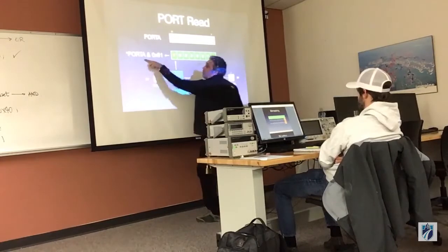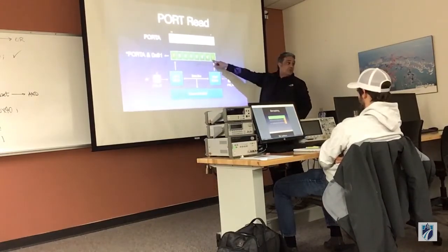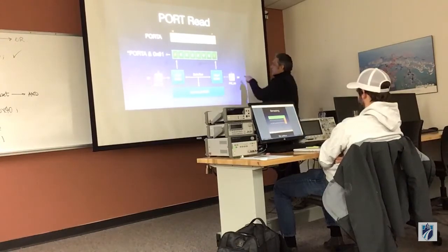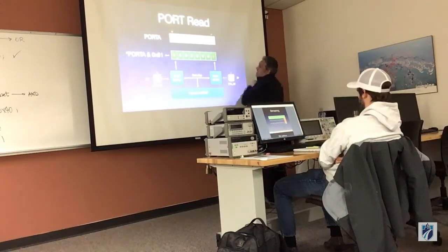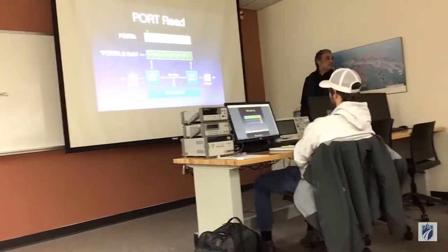So that when your port instruction gets hit, you actually see that logical 1. So, if you set up your system as a read, 5 volts in the outside world will look like a logical 1 in the port register. See that?